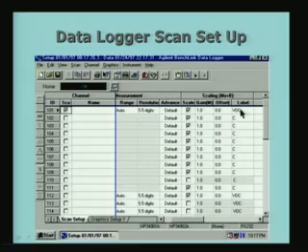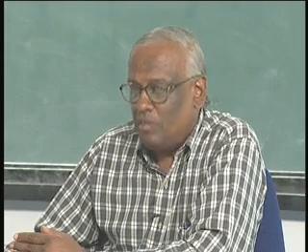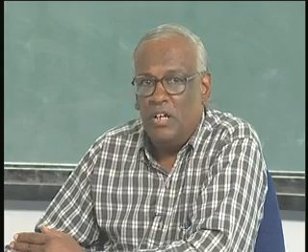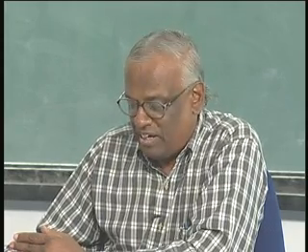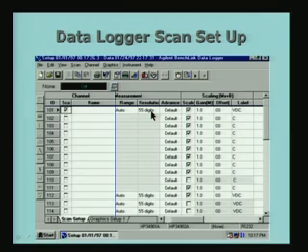In this case I have labeled it voltage DC. So, this channel is now available to measure output in voltage DC with a 5.5 digit resolution, and we will immediately see on the board that this is suitable for measurement of voltage output from a thermocouple. Why is it so? Let us just look at that.